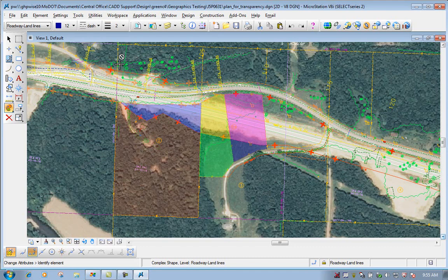Another little tip that you can do, and like I said, this is very optional, is whenever you make shapes out here, just like what I just did, it may be a good common practice to place all those shapes on a certain level, like one of levels 1 through 63. You could actually apply it to one of those, since those deal with the old leveling scheme that we had.